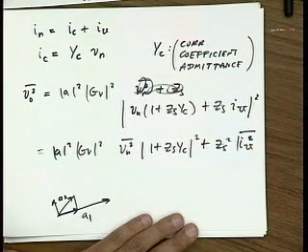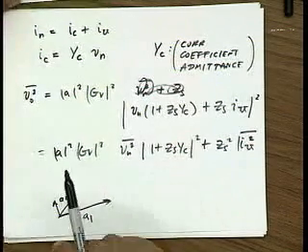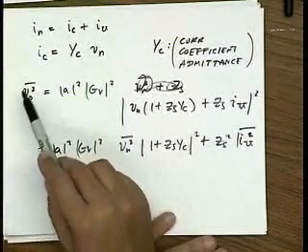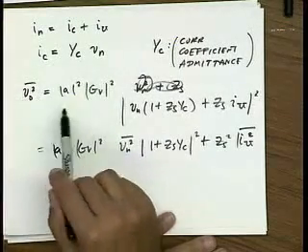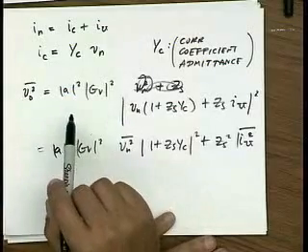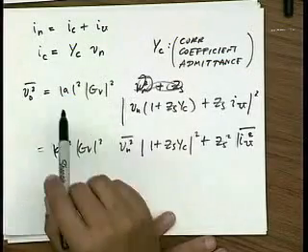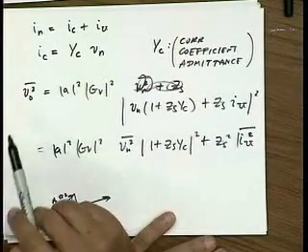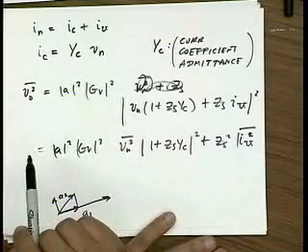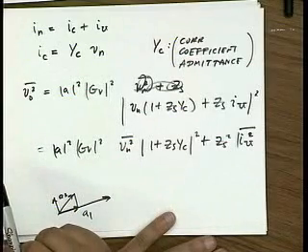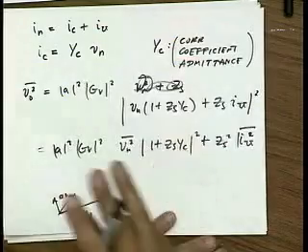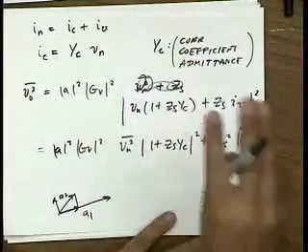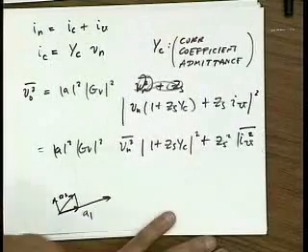I guess, why are you taking the dot product of that specific value with itself? That is my original question. So I want to find the RMS value of the output noise, right? And if these random variables are independent from each other, I can just sum their individual RMS values, right? That's what we did last lecture. This lecture, though, we're saying these two variables that I'm summing are partially correlated. So if I want to find the RMS value of the sum, it's not simply equal to the sum of the RMS values. I have to take into account the correlation. So this is what we've done now.